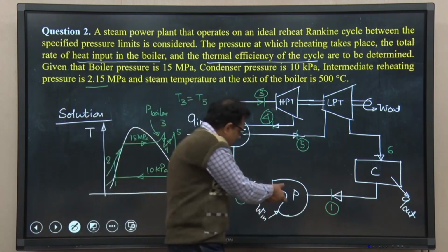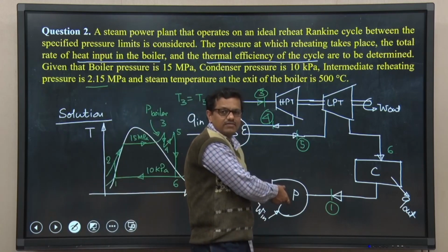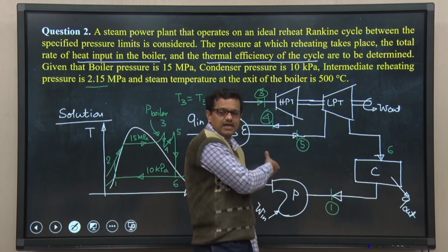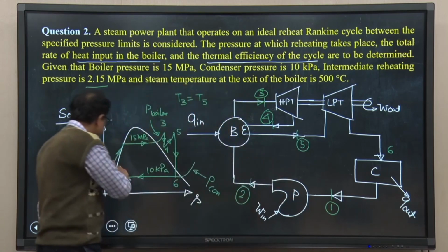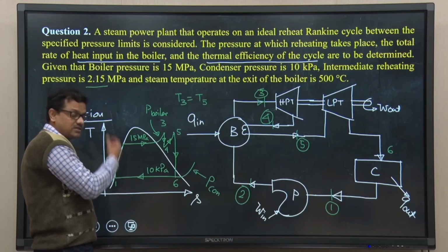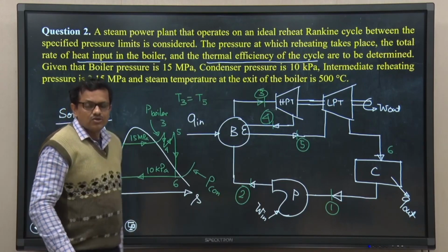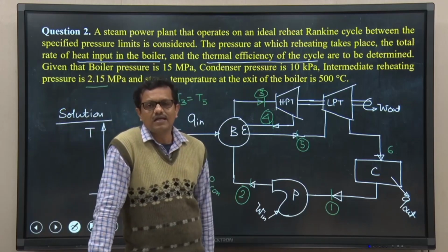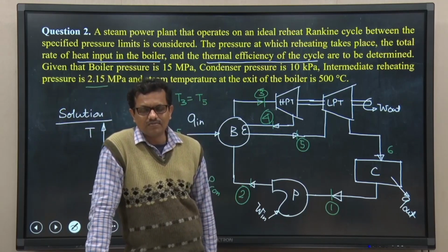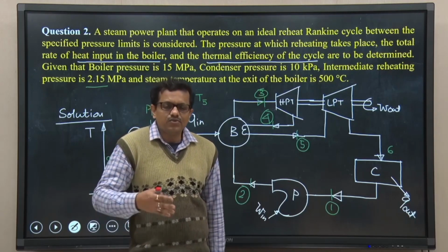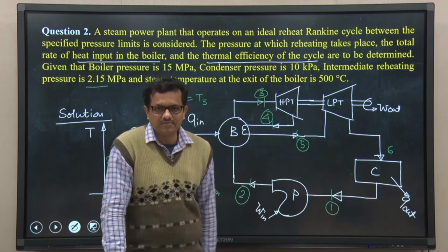This is not a heat interacting device, this is a work interacting device, and the process we have seen is an isentropic process, you can see from this TS plane, that is a reversible adiabatic process. So long as the process is reversible, entropy generation is equal to 0, and the process is not interacting with the surroundings in terms of heat.